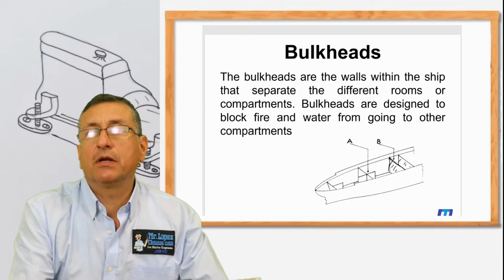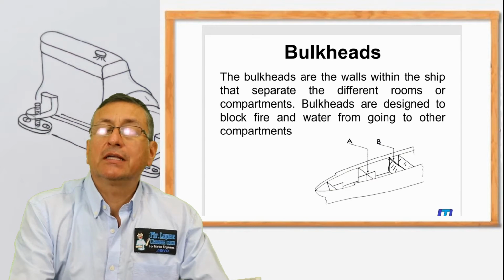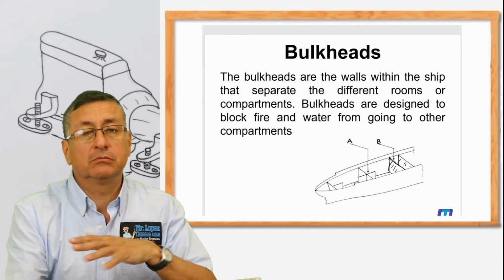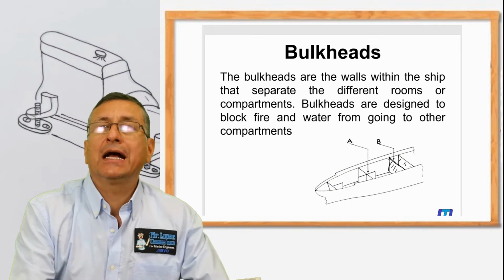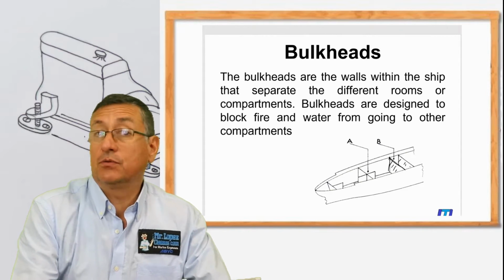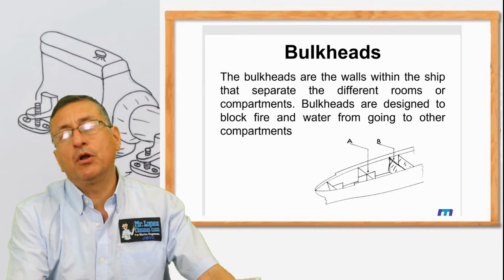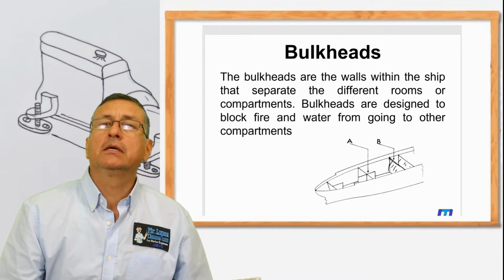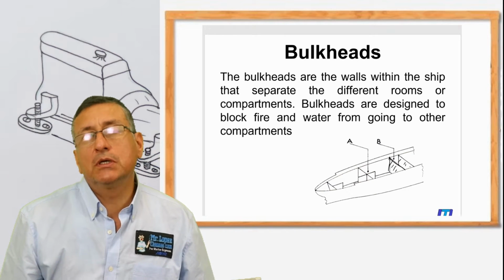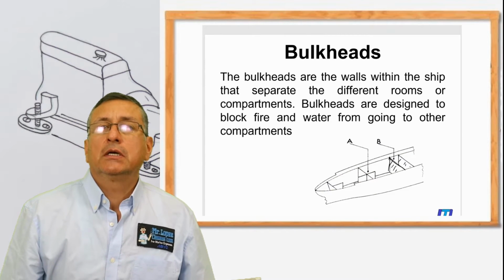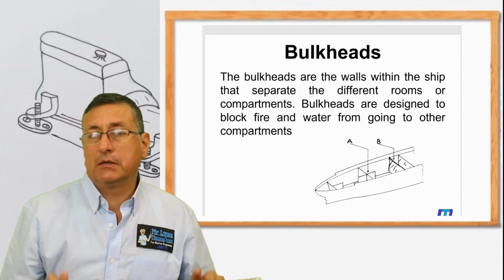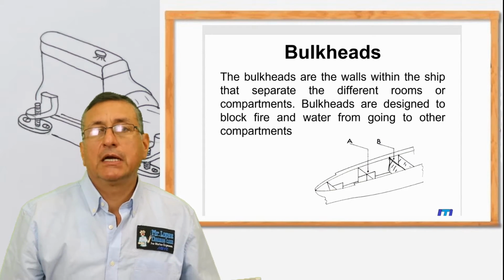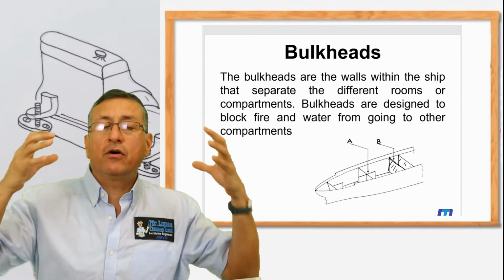That wall is a special wall, for insulation, for everything, because that's the separation between the engine room, with a lot of noise and a lot of temperature, and the cabin. Okay, this is one of the bulkheads. The majority of the bulkheads are non-structural. However, in some small boats, they are part of the structure. In big boats and mega yachts, it's considered that they are not structural. But at the end of the day, they are part of the structure.